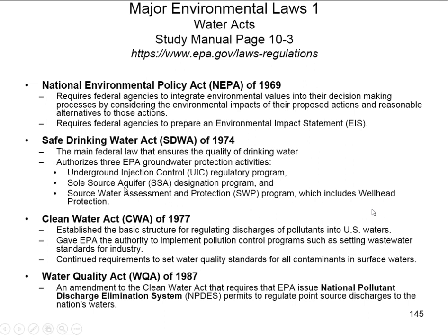Safe Drinking Water Act. This is really important because it ensures our quality of drinking water. And so we have some of these programs: Sole Source Aquifer, Source Water Protection Program, Underground Injection Control under the Safe Drinking Water Act. Clean Water Act established industry standards. And the Water Quality Act is one that requires the permits, the NPDES permits, to regulate point source discharges.